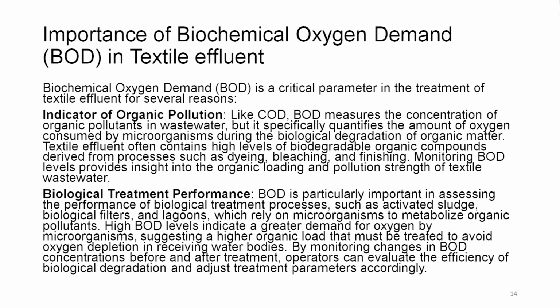So, depending on the load of the organic pollutants, this adjustment has to be done continuously, because the microorganisms have a limited source of oxygen in the dissolved form in the water, and if they do not have enough to consume, to be able to function and degrade the organic pollutants, then the microorganisms will die due to lack of oxygen.